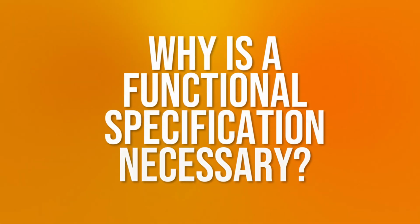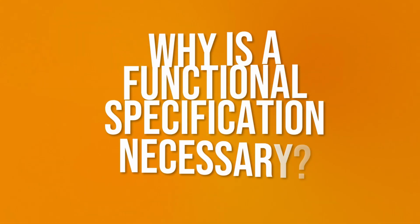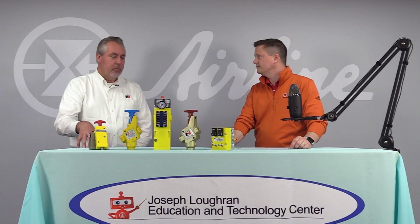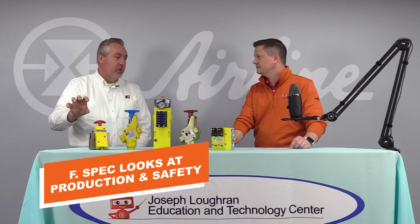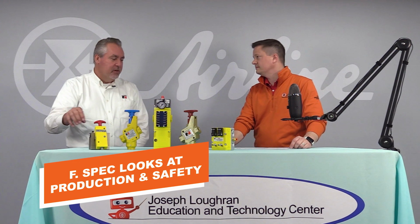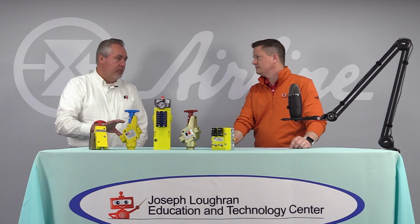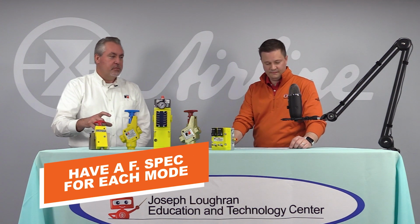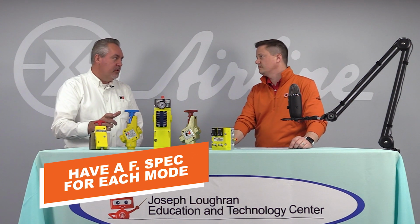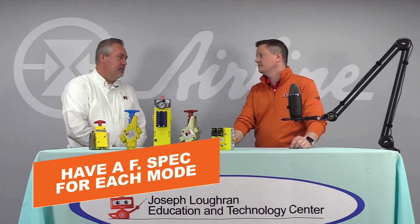Why is a functional specification necessary? Well, if you do the risk assessment right and you've used the right people, you know how the machine needs to operate for each mode of operation. That functional specification will determine how it needs to work during normal production to gain the most productivity out of the machine and make it safer. And then, what needs to happen when you're in manual mode? What needs to happen when you're in teaching mode, for example? So each mode of operation should have a functional spec that defines what the safety needs are. That way it's designed into the system.